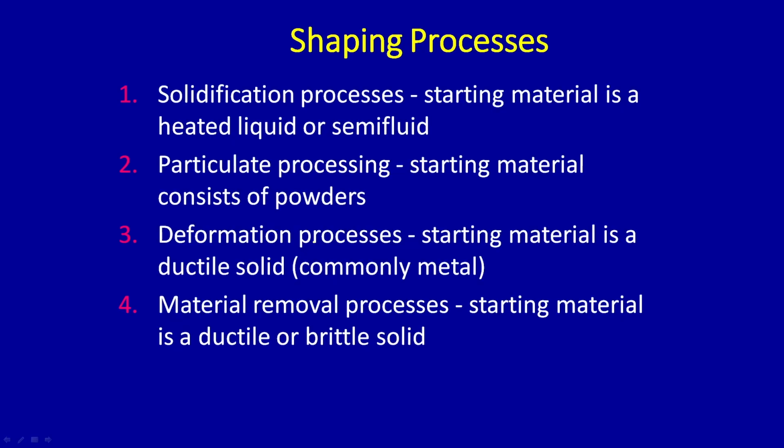There are many such objects produced from that. How many of you know that on missiles some of the fins are made of pure tungsten? Why? Because they can withstand high temperature. When a missile moves at a very high speed, the friction with the air can generate a lot of heat, and it can melt even many things in the world. So we have the choice of using only tungsten, but then we have to make solid tungsten. How do you give the shape of the fins? It is done by powder processing of the material, which is called powder metallurgy, or PM.